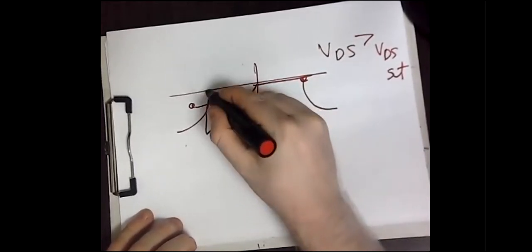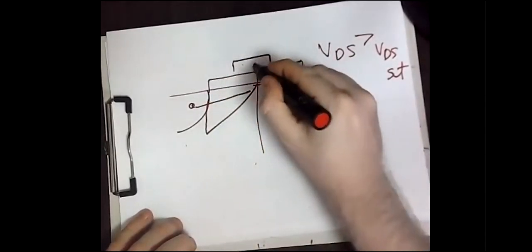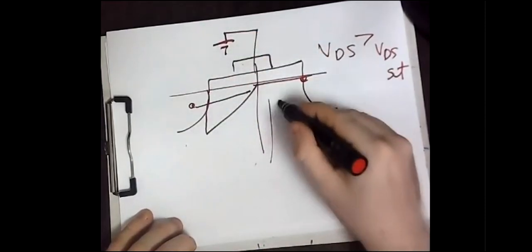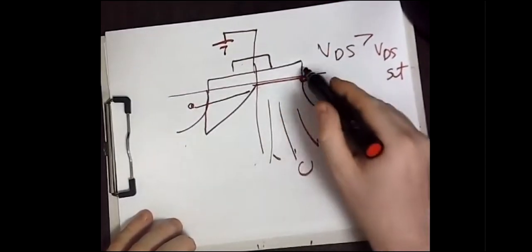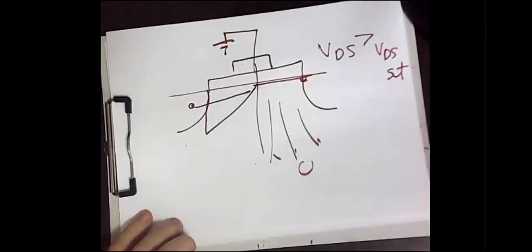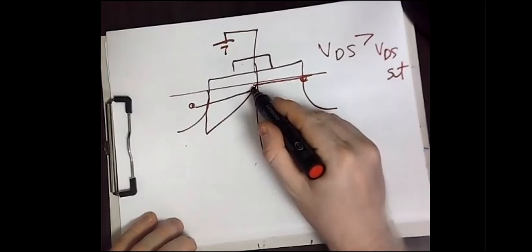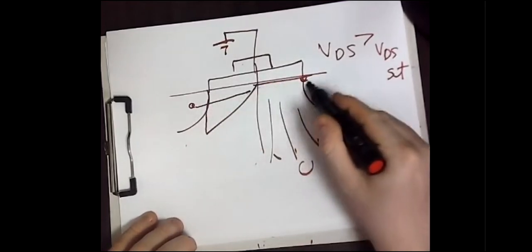And it's not a p-type because please don't forget that you have a positive charge applied to the gate. So this positive charge will repel holes from this region, so this region becomes a depleted region. Accordingly, we have electrons here, and this is a channel, but now this is a depleted region.